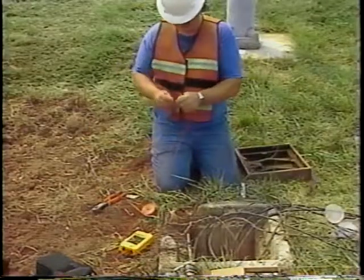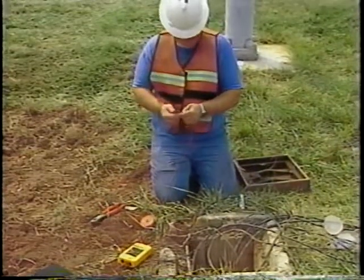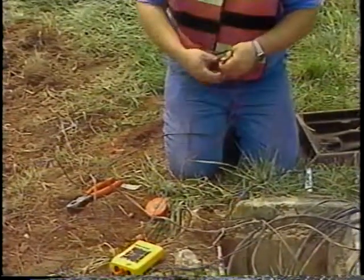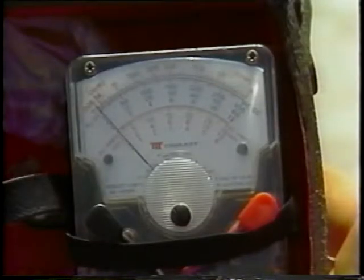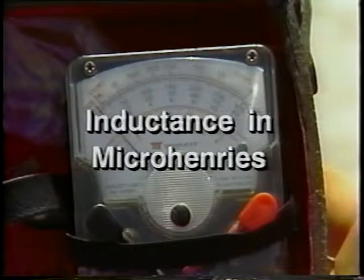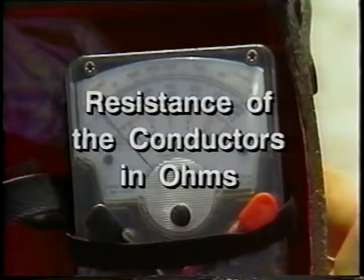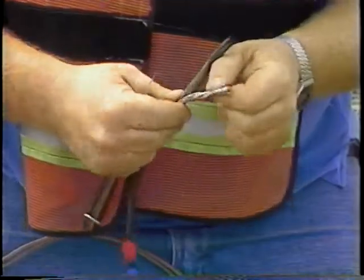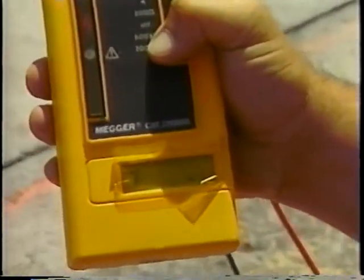Now that you have inserted the wires, installed the pull box, and terminated the conduit, you must test the loop. A loop tester instrument capable of checking the wires' induced AC voltage, the inductance in microhenries, and the resistance of the conductors in ohms should be used. In addition, you should check the integrity of the wire insulation using a megohmmeter or megger.